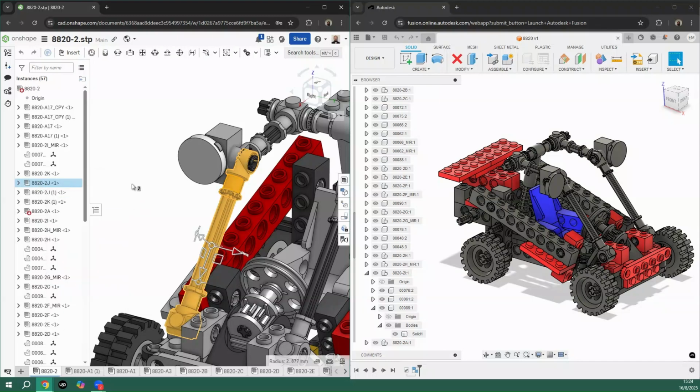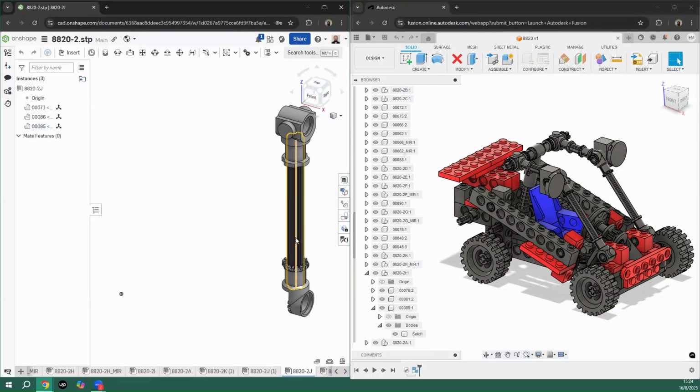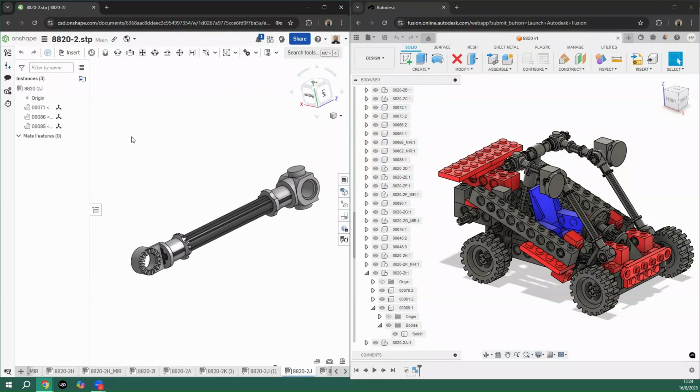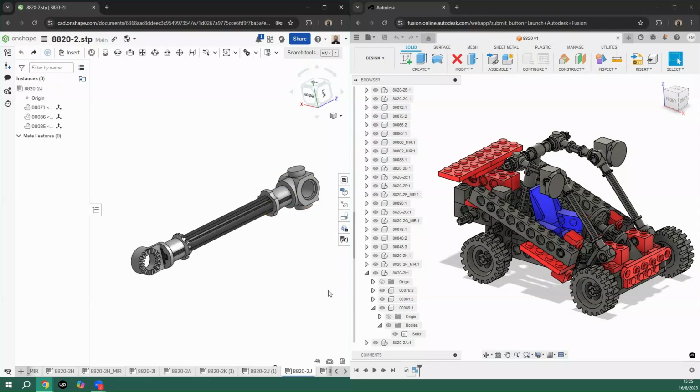What I'm going to do is right click on the assembly here at the model tree and click on switch to. Okay, so we have the assembly with 3 parts, and as you can see, it has a marker here on the model tree that shows that this part is actually totally free, so I can drag it all over the place. They are completely floating without restrictions. Okay, so I'm going to undo these operations to get them back in the correct position.